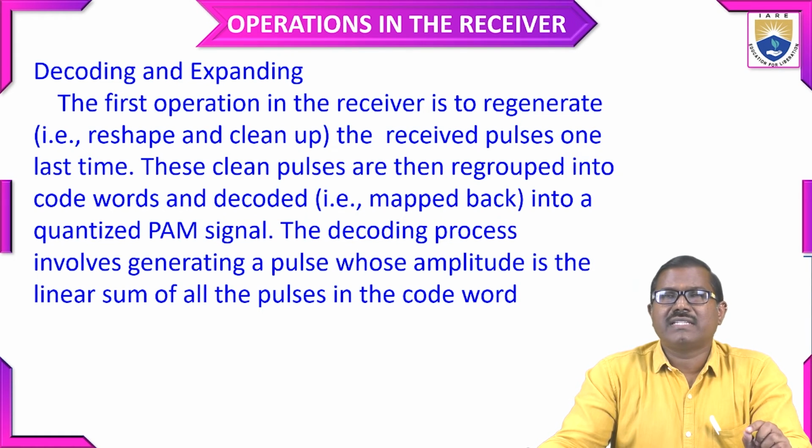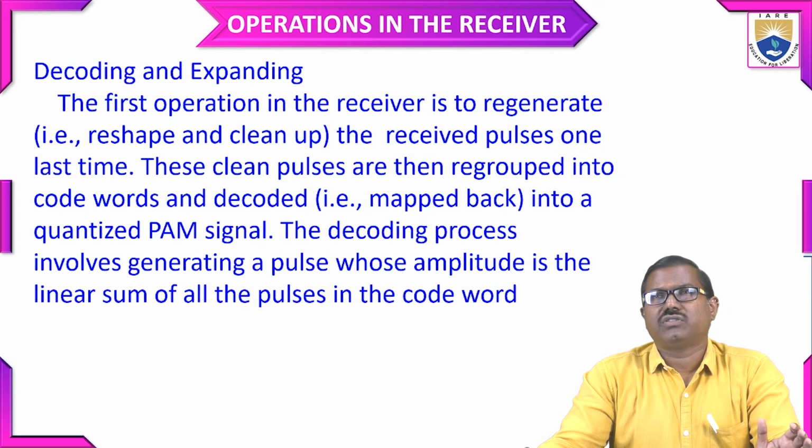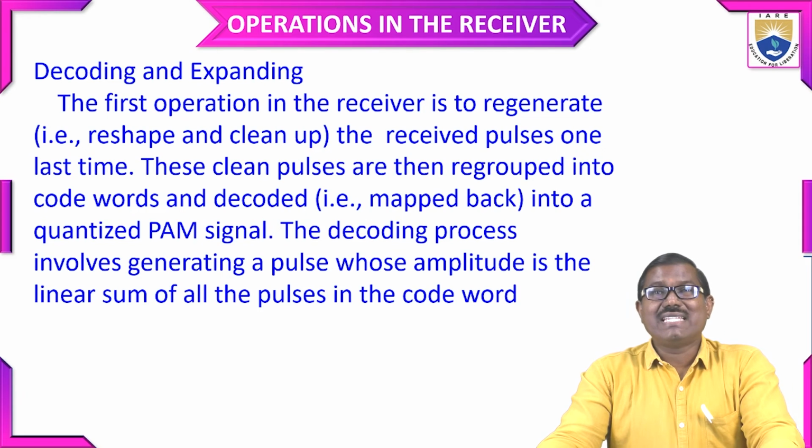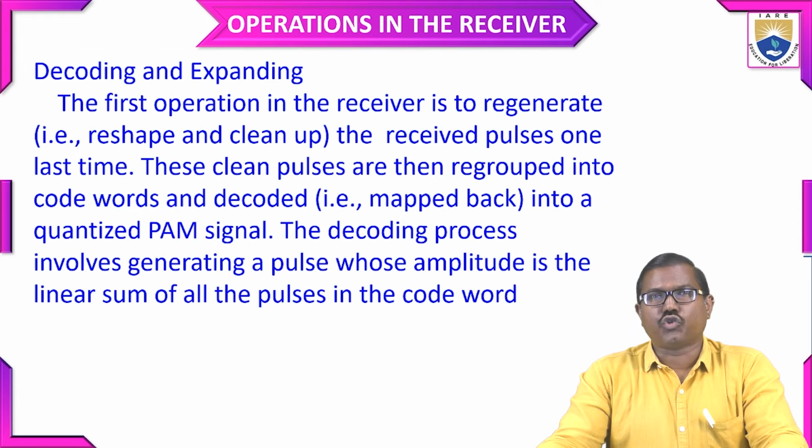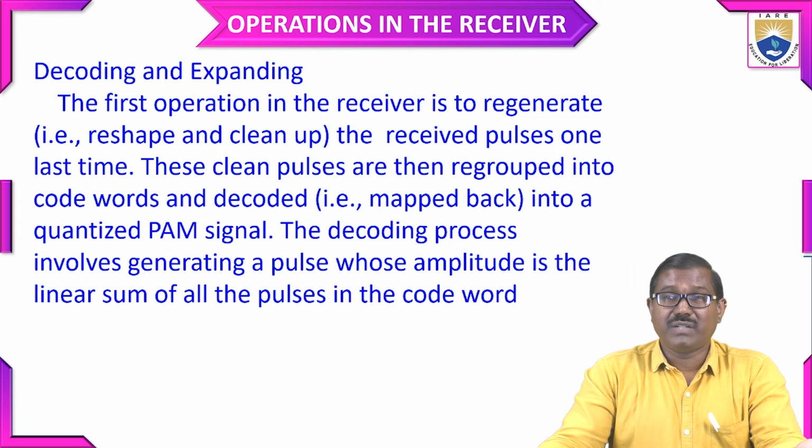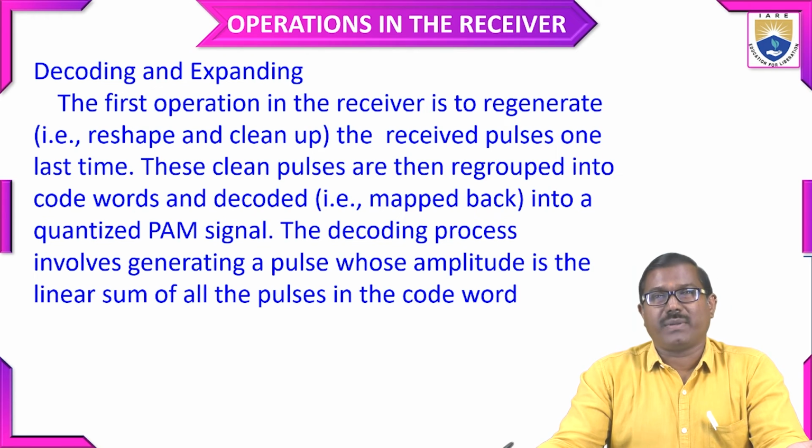So here the regenerative repeater's duty is reshaping and cleanup. So the received pulses are cleaned up. These clean pulses are then regrouped into code words and decoded into a quantized PAM signal. That means mapped back, reverse mapping.